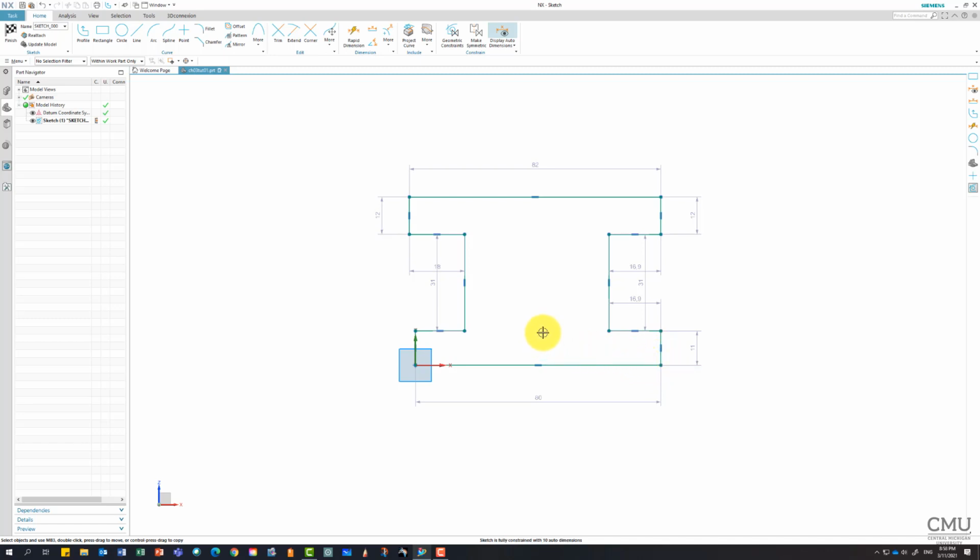To add more geometrical constraints in the sketch, if you are in the sketch environment, just simply type C, then you will be able to activate the geometrical constraint command. Then as you can see, there are plenty of constraints you can use. Also be careful with this automatic selection. If you are about to pick two objects, automatic selection is really handy. As soon as you pick one, right away it gives you a chance to pick the second one, and so on. We'll talk about this in the lecture more.